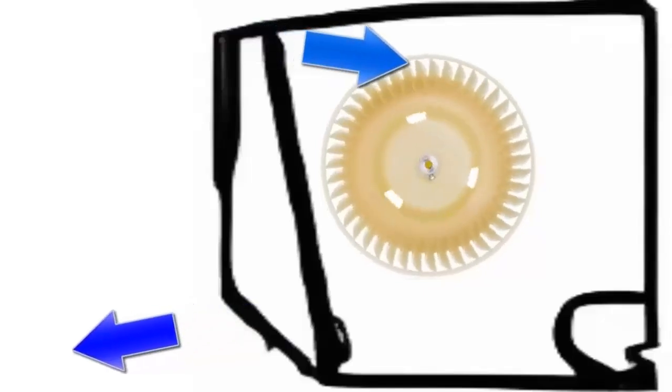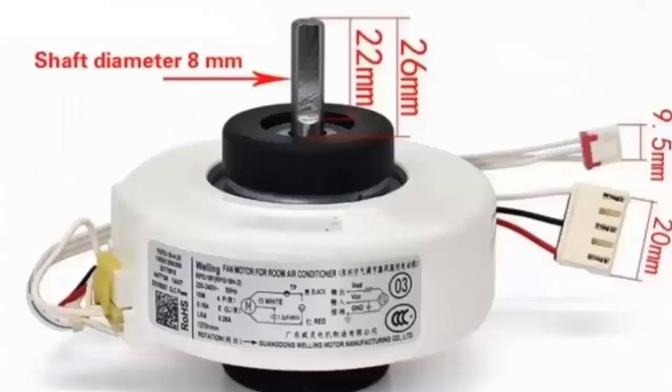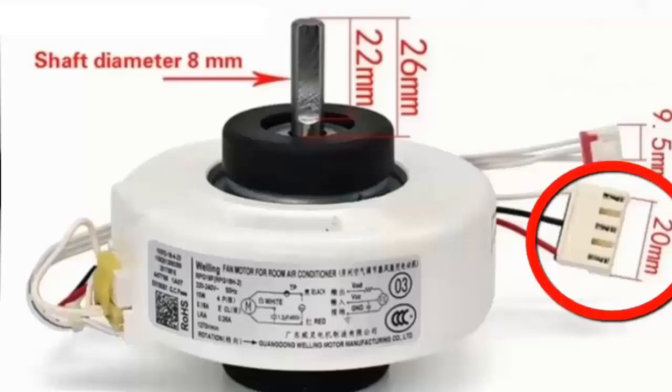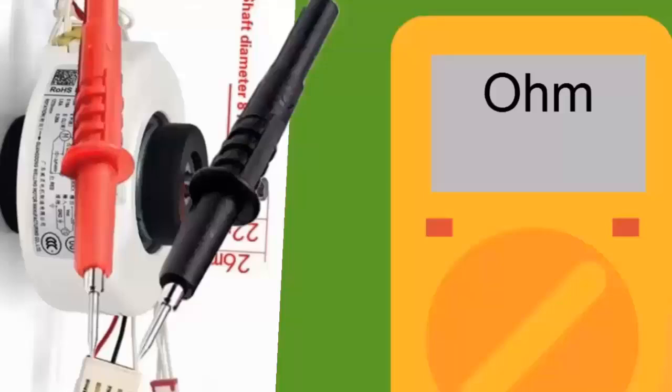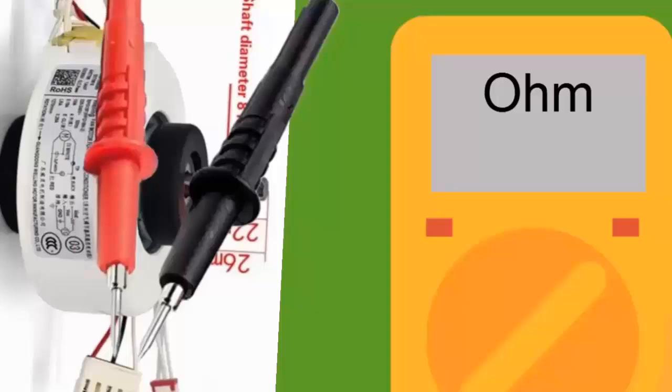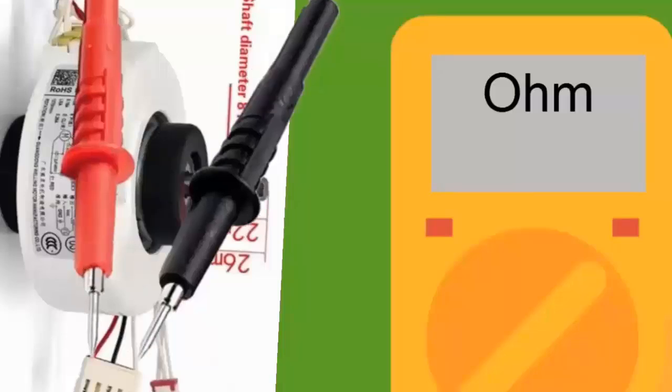6. Measure motor resistance with the motor disconnected. Use a multimeter in ohms mode to measure resistance between thick wire pairs of the motor. No measurement should be zero or infinite. If any are, it indicates a motor winding issue. 7. Motors without capacitor or DC motors. Check resistance between thick wire pairs. All three readings should be equal. If not, there's a problem in the motor windings.